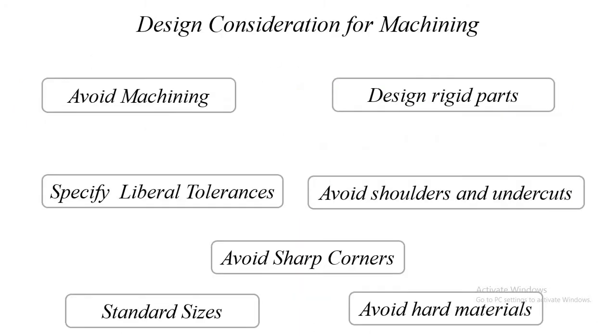Now, let us study the design considerations which are required for making machining drawings. Exactly where do we use machining? Components requiring high accuracy and precision, complete flatness, roundness, parallelism, parts having relative motion with each other and interchangeable assembly are few applications of machining components.